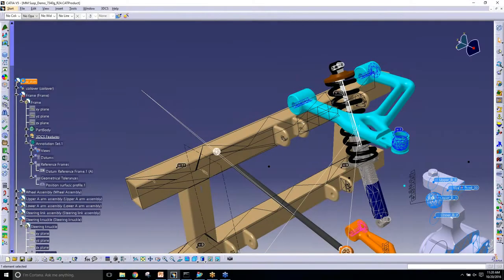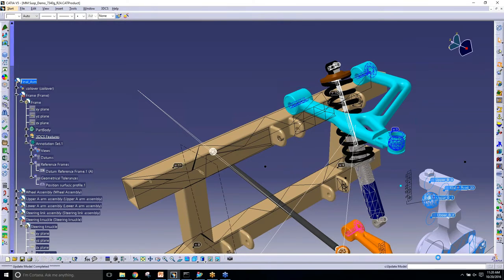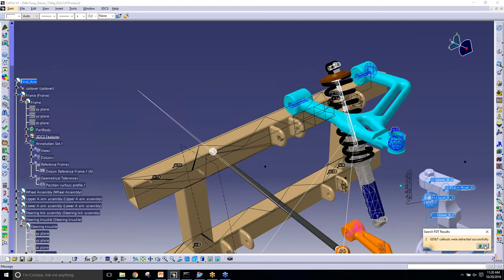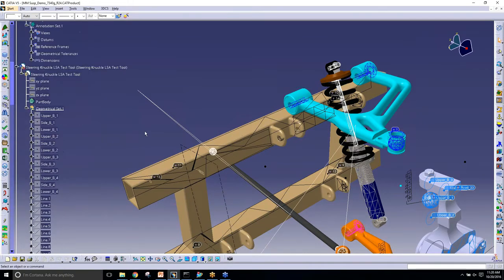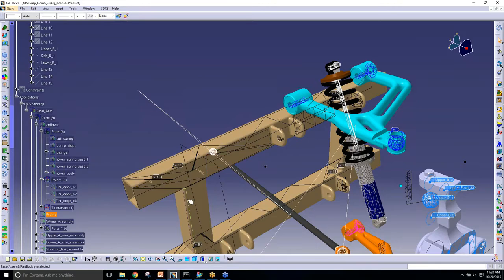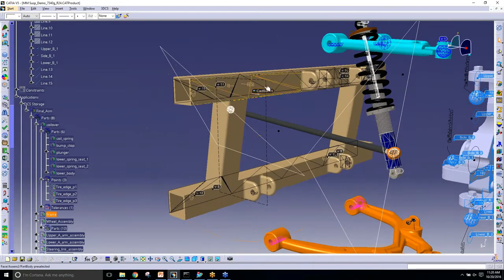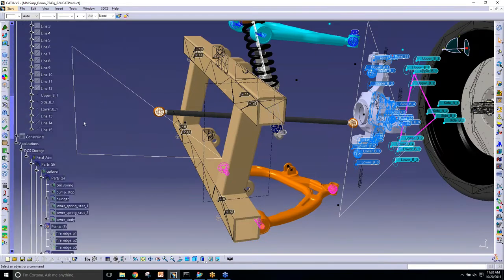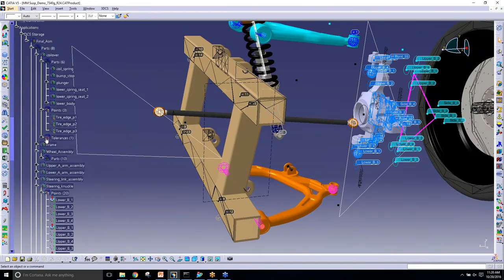All right, going back up to 3DCS, and I'm going to update the model. I am going to update the GD&T, and I can just select the frame or select the whole part or the whole assembly. So I just got the two. And what that's going to do is actually create all of the features, it brought over the points. Here's the frame, and here's our GD&T.